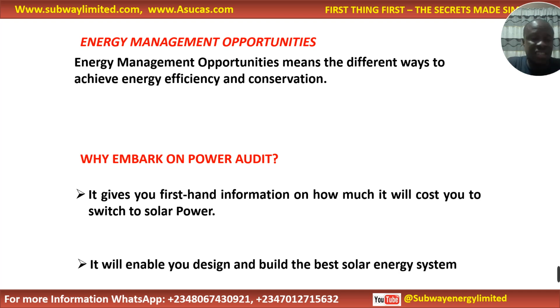So we cannot just design a system and give somebody a quotation without visiting the site. What if you go and the solar panel plane is too far from the powerhouse? Where will you get money to buy the cables? If you do that, the client has already paid you, you get to site and you require so much length of cable, you will try to maneuver your way so that you don't run at a loss or use your money to buy cable.